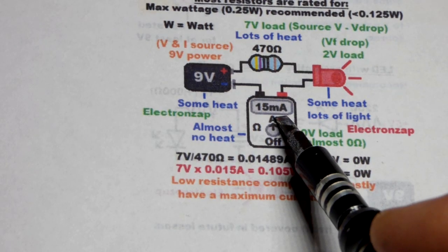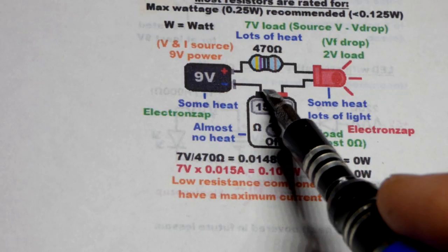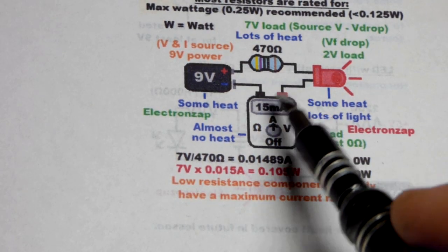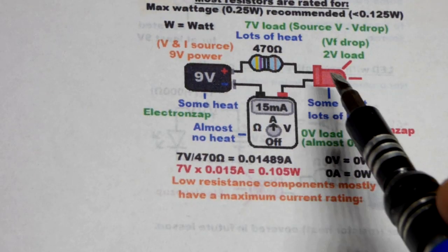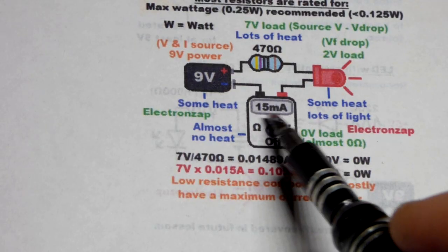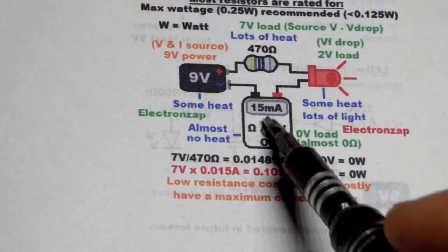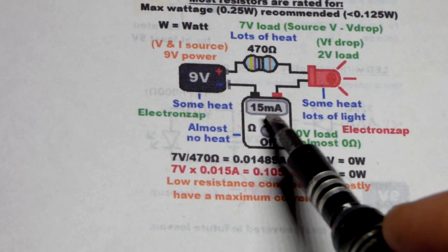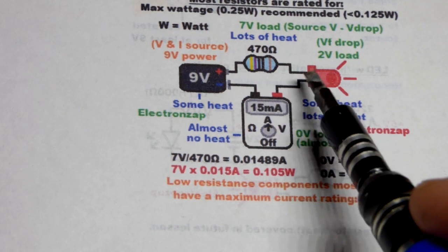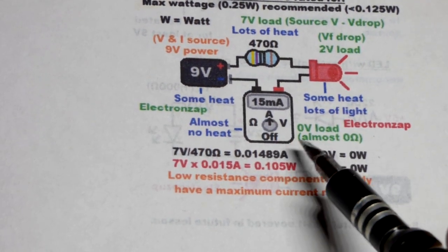But for smaller measurements like this, generally you got a multimeter. You open up the circuit, so maybe there's a switch that opens and closes. You could just put the meter across the switch. So even though the switch is open, the current will flow through the meter. The LED will turn on, but you'll be able to see how much current is flowing when you don't have the meter and the switch is closed. Hopefully that makes sense. But for measuring current, you have to get the current flowing through the meter for most of them in order to read it.